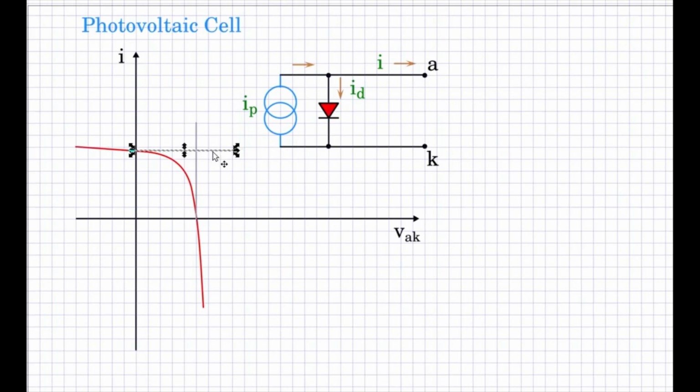The constant current line, if you take it, gives an idea of the slope of the constant current portion, and therefore it implies the existence of a shunt resistance, a high value of shunt resistance across a constant current source. So we can include this non-ideality, a high value of shunt resistance across the constant current source as shown here.